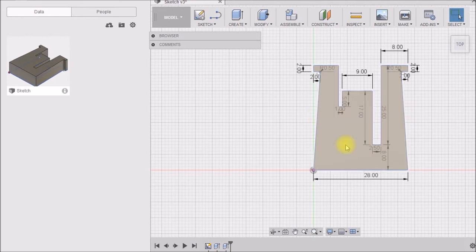And then the fourth time I redrew the sketch was due to the way I had dimensioned the part. I think when I originally drew the part, I put an overall height in here of 33 millimeters. Now what I did to fix that in the last version is I put all of the dimensions inside here. So the overall height is 8 millimeters up to the bottom of this slot, and then 25 up to the top of the clip. And in doing that, this internal geometry here stays fixed. It doesn't move around if I change the outside dimensions.